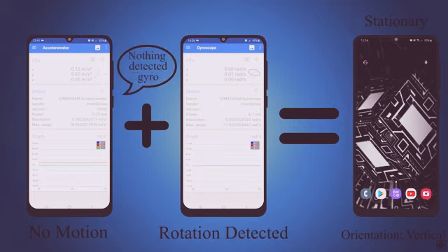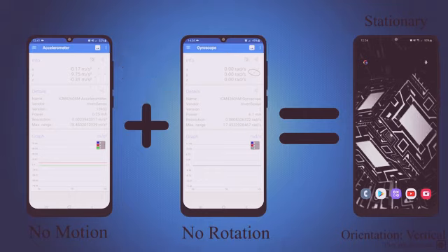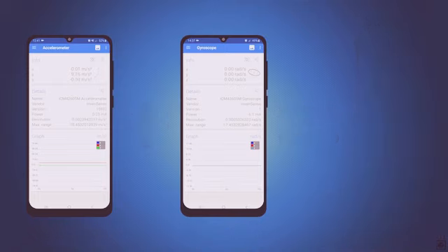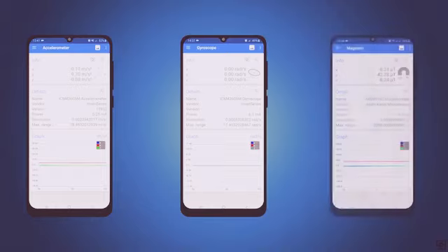Similarly, the accelerometer can be used to recalibrate the reference frame of the gyroscope and get a more correct and consistent rotation. Whenever the device is at rest, the output of the accelerometer equals the gravity vector. And drift can be periodically corrected by using the gravity vector from the accelerometer. With these two sensors, we use one more for the orientation of the phone. It is called a magnetometer.